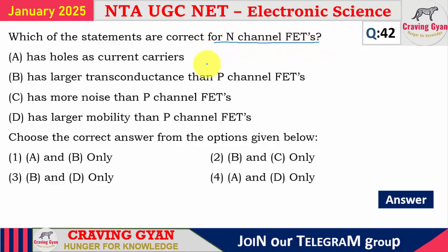42nd question, which of the following statements are correct for N-channel MOSFETs? In the case of N-channel, the holes will be acting as current carriers. No. In the case of N-channel, electrons will be acting as current carriers. N-channel MOSFETs will have a larger transconductance than a P-channel. It is correct. It has more noise?